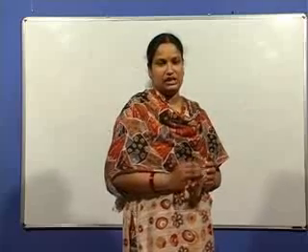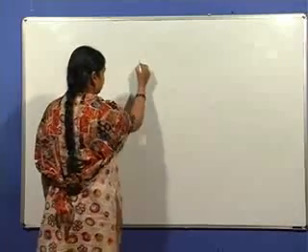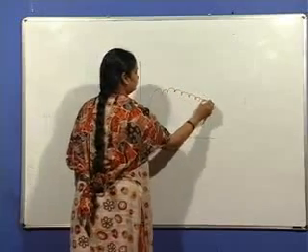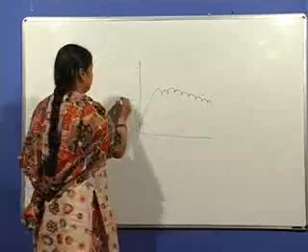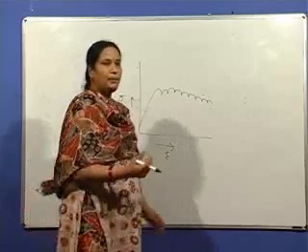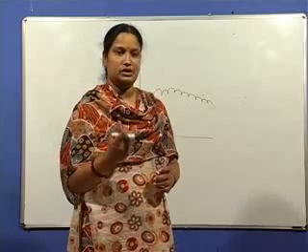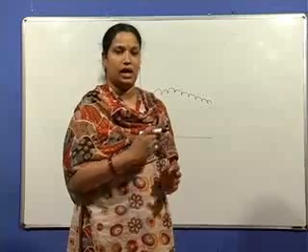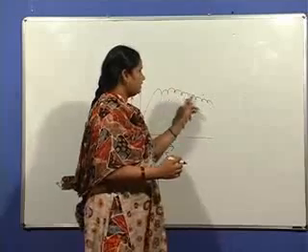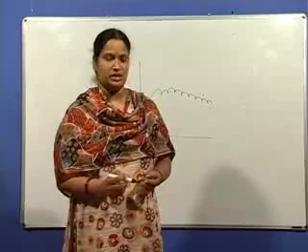Because of this dynamic strain aging, continuous fine serrations are seen in the stress strain curve. This is due to the solute atoms which rapidly diffuse to the dislocation core and try to lock them, and the dislocations get locked and unlocked, locked and unlocked. So this process repeats, thereby fine serrations are seen in the stress strain curve. This is for the case of dynamic strain aging.